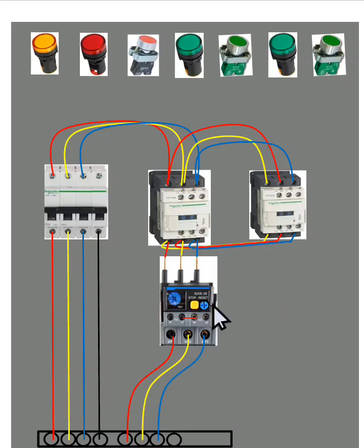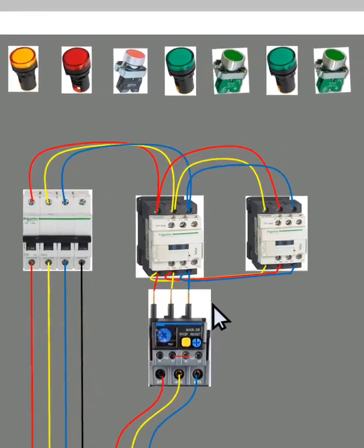So you have your overload relay. When the current being drawn by the motor is trying to go up, this overload is set in such a way that it will cut off the control of the circuit. When the control is cut off, the contactors are off, and the power is prevented from going to the motor. You can see the power diagram looks so simple.